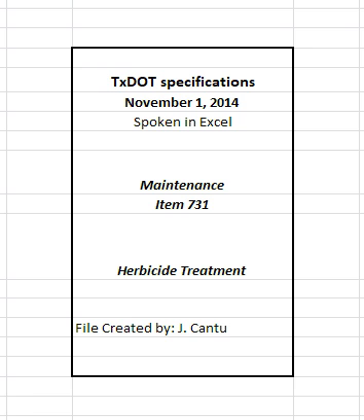7.2.4 Supports, sign supports, luminaire poles, mailbox supports, etc. Spray a 12 inches wide band around and on all sides of the base of signposts, luminaire poles, mailbox supports, or other roadside hardware within 10 feet of the pavement edge. 7.2.5 Handgun applications. Use a handgun to spray structures inaccessible to spray with boom mechanized spray equipment.